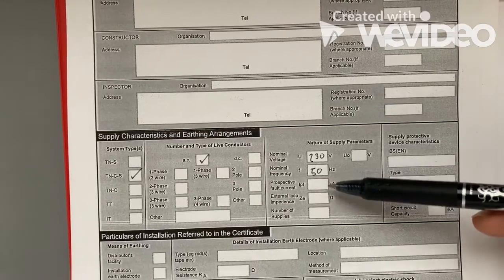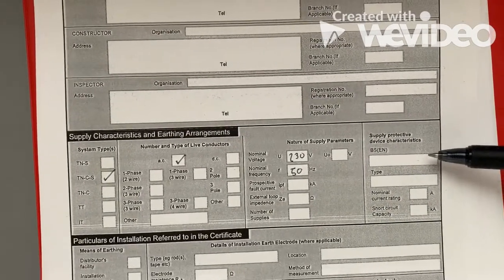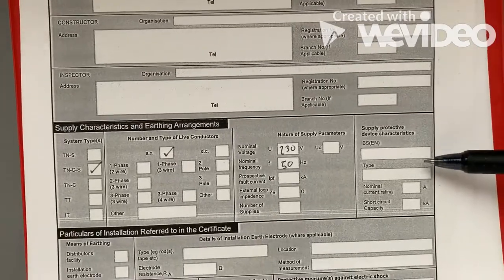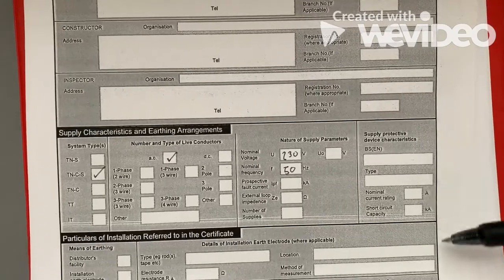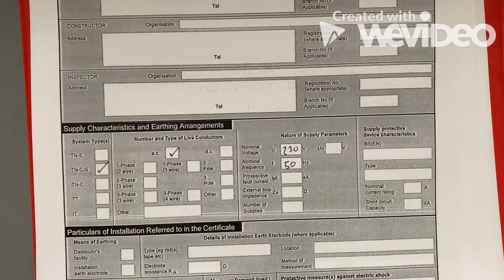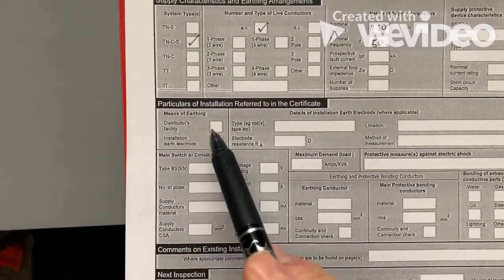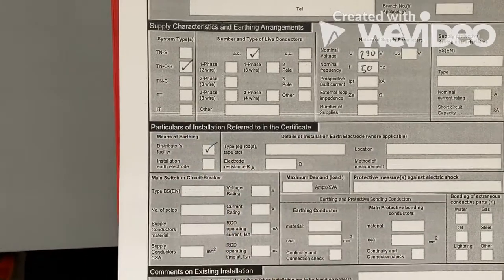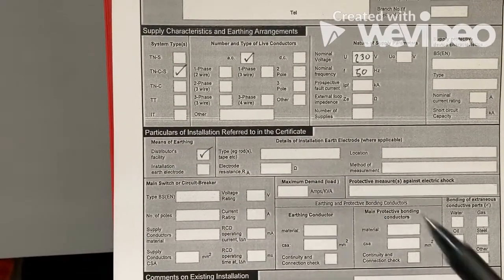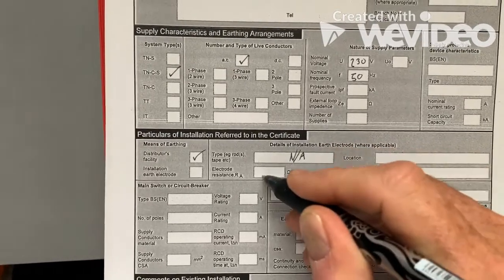And then what we'll do is we'll measure some of these things in here and the supply protective characteristics. So the type of the breaker, the BS number of the fuse and the type, and we'll have a look at those in a minute when we go through it. And then we have here is means of earthing. So is it a distributor's earth? We haven't said it's a TT system, if it was. So we haven't got an earth electrode here. So we could put NA for these details.